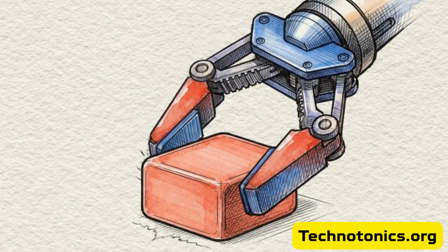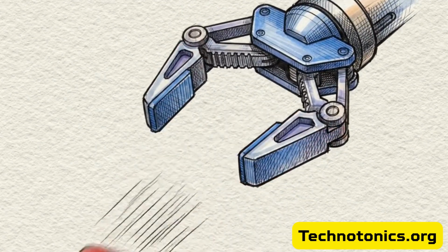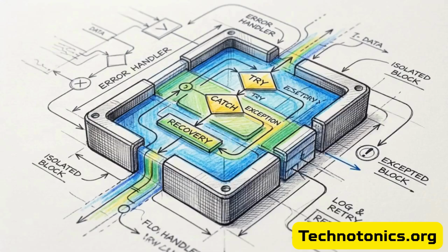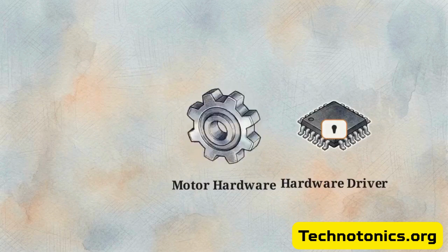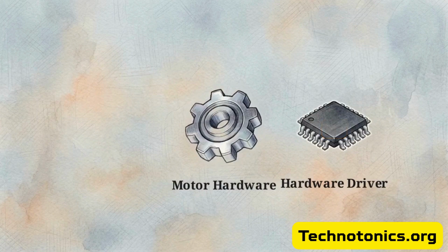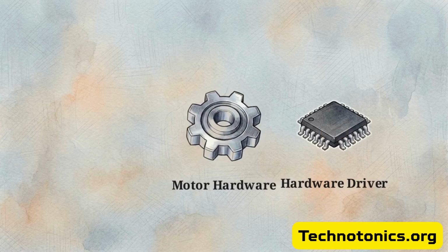In robotics, physical errors are a certainty. Sensors will eventually disconnect and hardware jams will occur. A script without error handling will simply crash when it encounters a hardware disconnect, leaving the robot in an unmanaged state. We implement specific try-except blocks to catch these anticipated failures, allowing the software to respond to an error rather than just failing. This allows for a cleanup phase, where the node can safely release hardware locks and bring the motors to a controlled stop before the process exits.